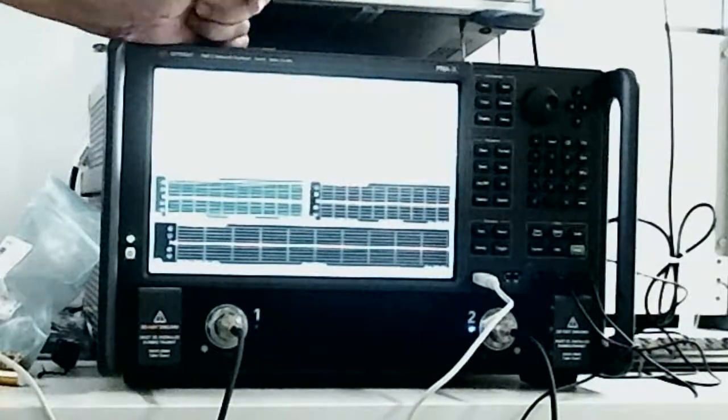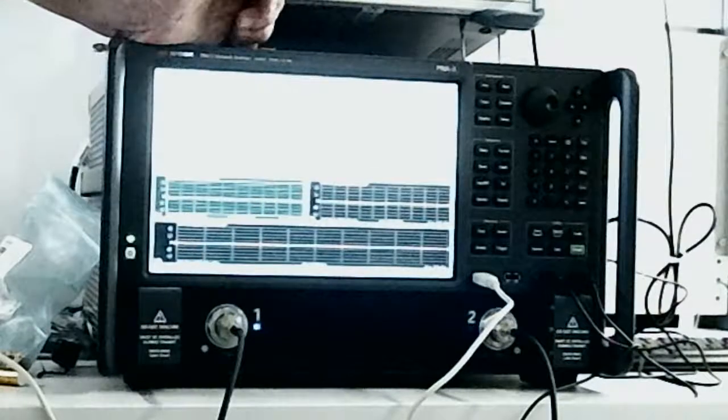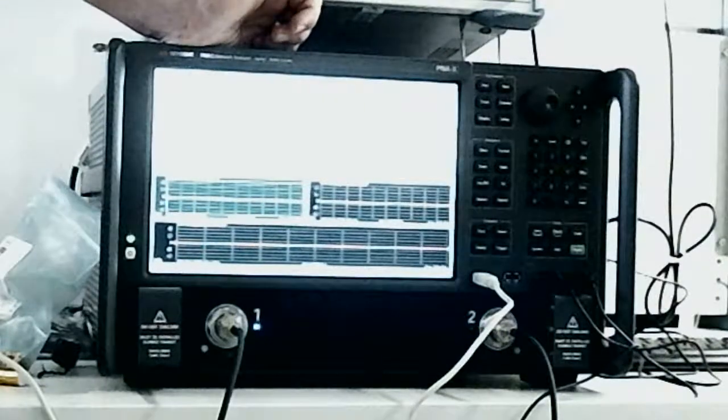Okay, so we've got power cal true. It's going to say what do you want to do the power calibration at. So it defaults to -5. We can set it to something else if we want to, but -5 is good enough. And then it's going to say, okay, it's 3.5 male is the default. That's fine as well because we're going to say that the amplifier is female. And then the last part here is the power meter settings, right?